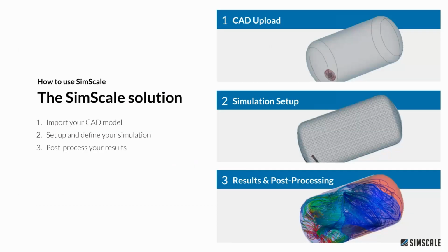So how to use SimScale then? In case you're unfamiliar with any computer-aided engineering workflows, you generally start with a CAD upload. You would create that in your CAD program, be it Onshape, SolidWorks, you choose. Upload your geometry to the platform, and then we go through some simulation setup stages.